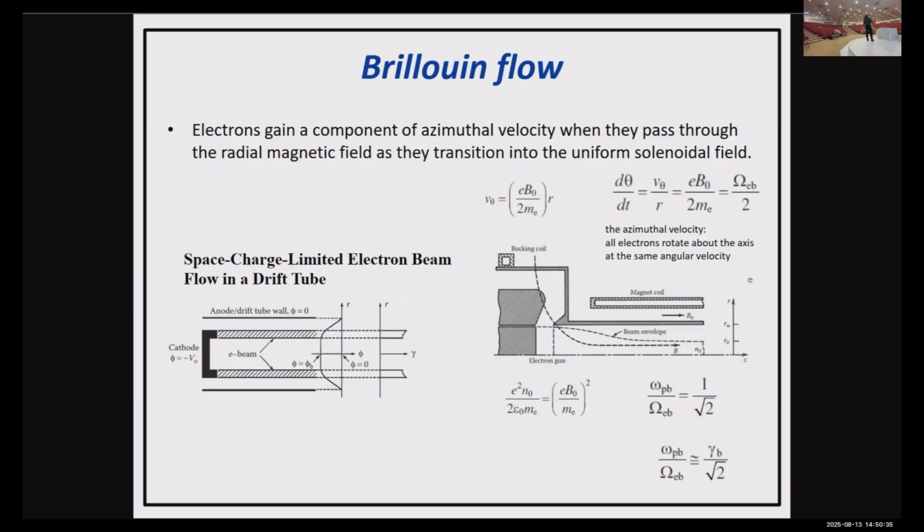For linear devices, the cathode, as I showed you in the lab pictures, is here, and the electrons will be emitted. If you want to solve your Laplace equations and differential equations, you divide the region into a couple of regions, region 1, region 2, and you need to assume the electron layer has a very thin delta thickness that does not contribute to the solution.